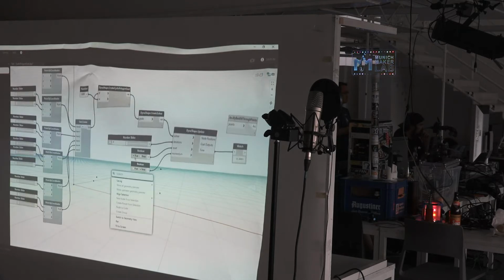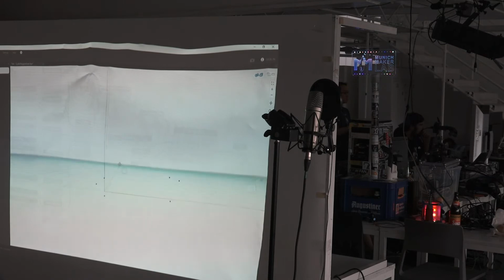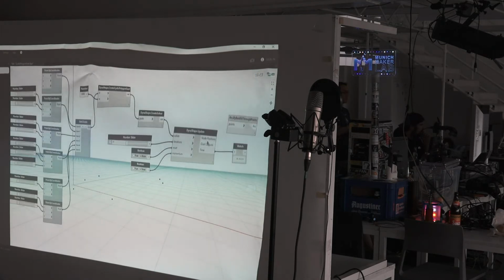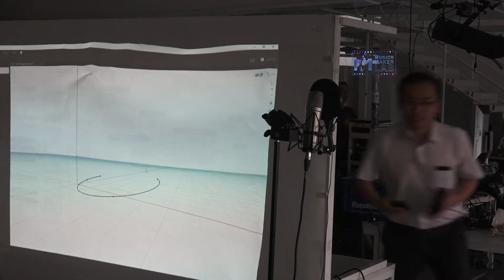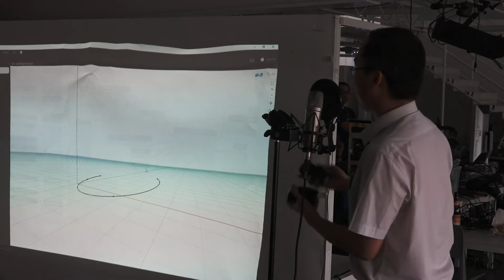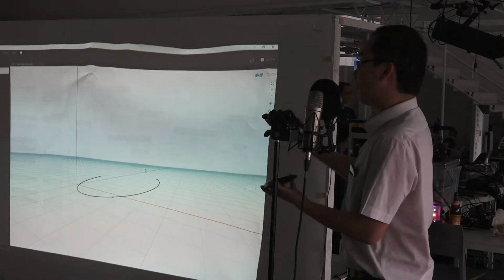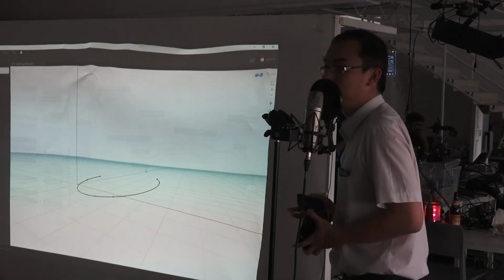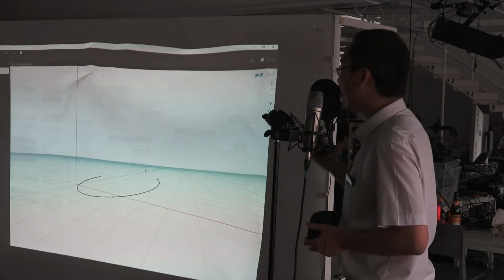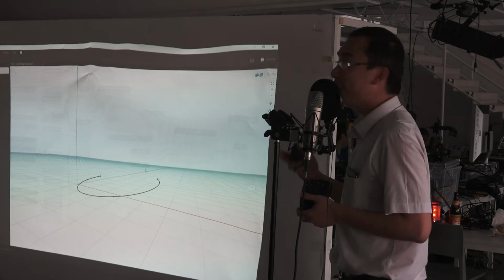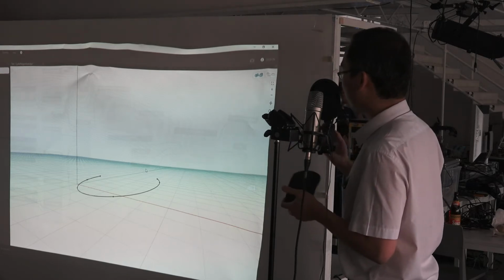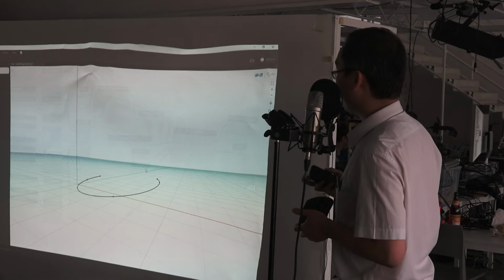So it's 3D for now, and then I run this over. Okay. So they snap onto the circle, and I can verify that they actually lie on a circle, like this arc here. So this goal is very simple, and you get a result right away, and probably you don't even need a solver to solve this simple geometric problem. However, when you have multiple goals that act on the same set of particles, and these goals are usually conflicting, then these goals start to become a useful design tool.